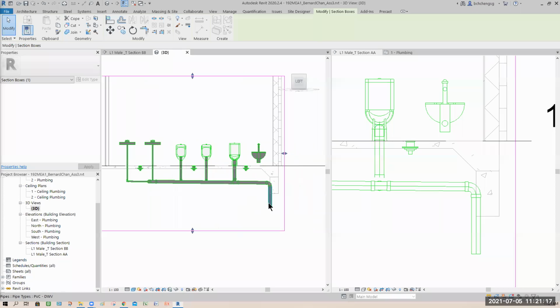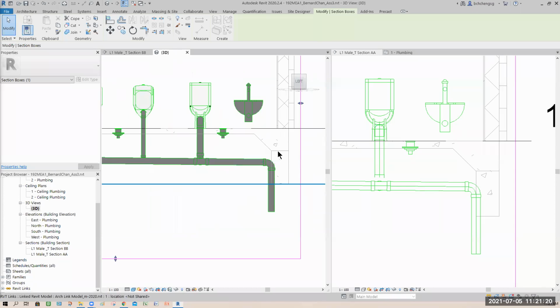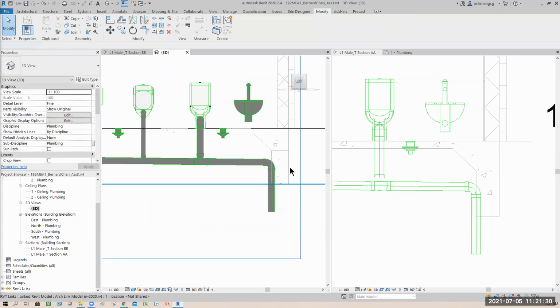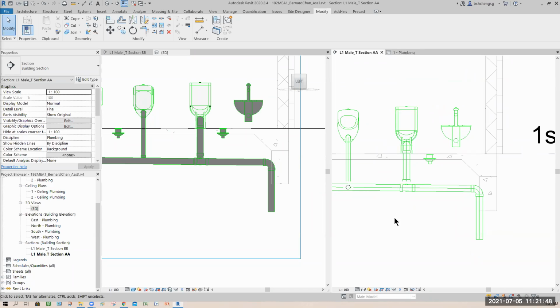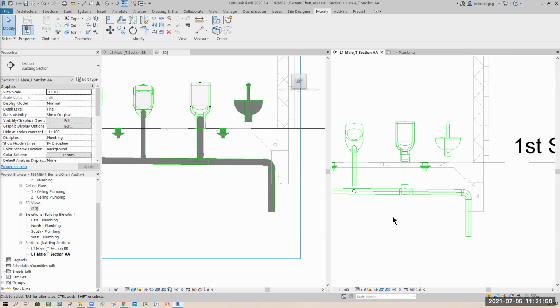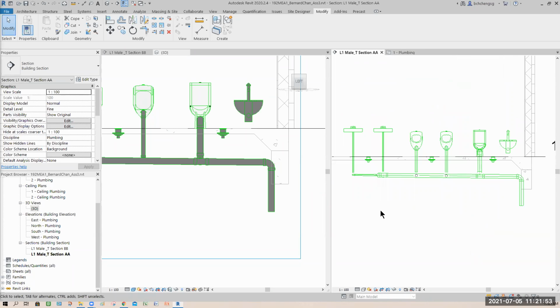You can't get your sanitary pipe clash on this. At least out, it should go up from here. Fine, they drill a hole, but not like this. Okay, this is the supporting beam. You cannot hack on a beam. No way. So sad to say, I got to redo all over again. I'm gonna cry. So you guys, same as me, right? Yes. So at least now you understand why, right?